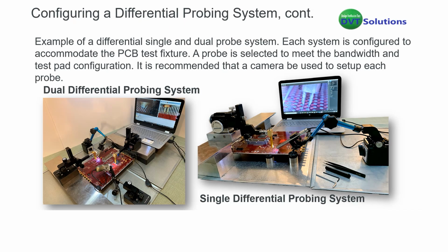It raises it up high enough that I can slide the board underneath. That allows us to probe anywhere into that board that's necessary, because the length of the arm of the manipulator is about 5 inches. So if you brought that manipulator right up to the edge of the board, you're only going to be able to probe into it about 5 inches. So if your board is, say, wider than 5 inches or 10 inches, then you might want to look at getting a probe bridge to assist the probing of it.